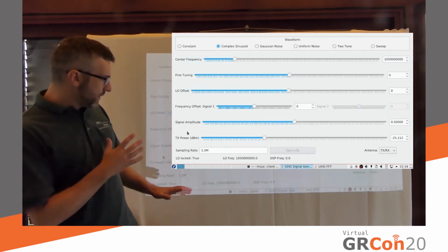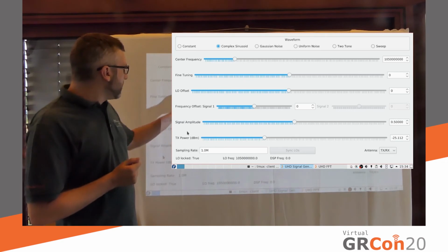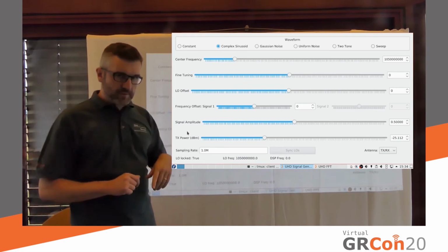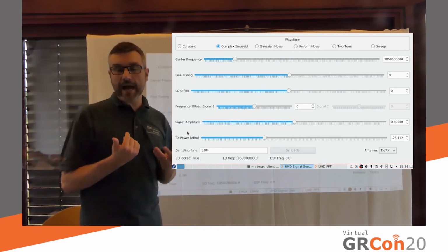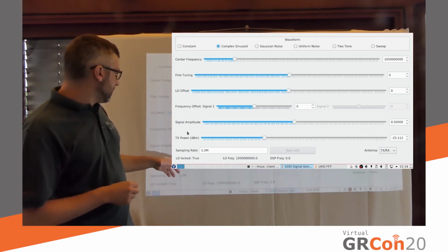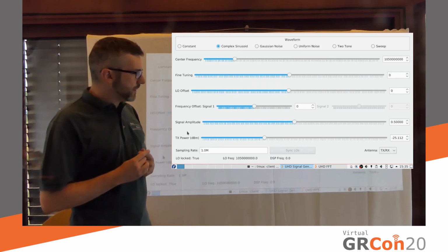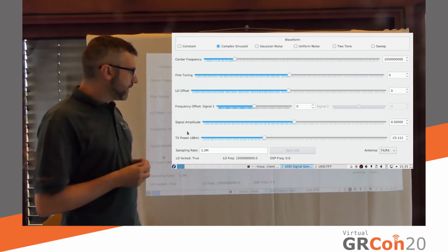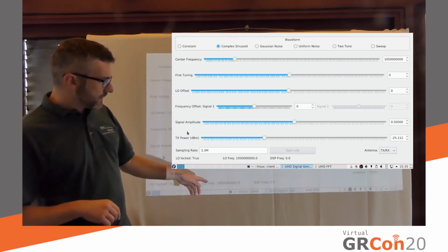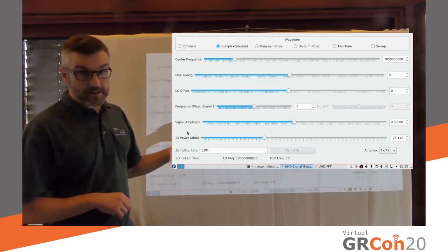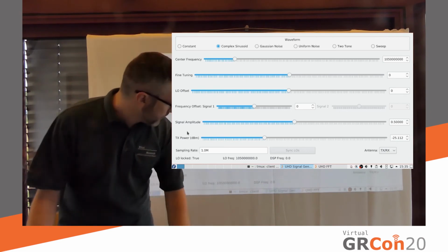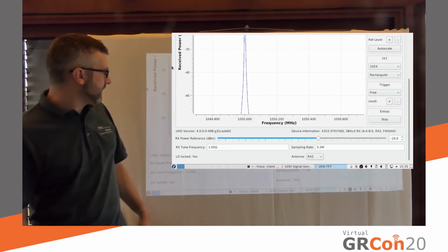The signal generator is a very simple application. I know that I'm transmitting a sinusoid. I know its amplitude. So in combination with the reference power level, I can now actually accurately predict the output power. So we're at like 0.5 means we're at -6 dBFS. So this application now, all it needs to do is set the reference power level to -19 approximately, and then we're done. That's it.